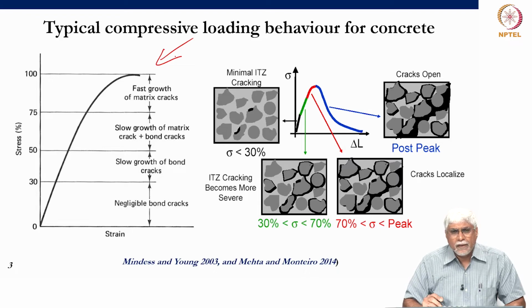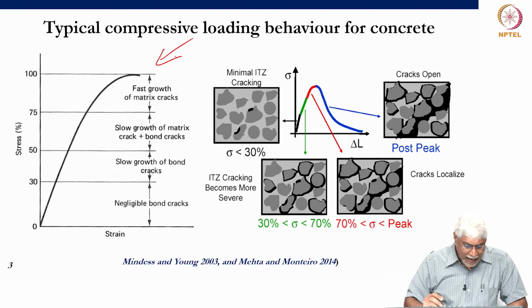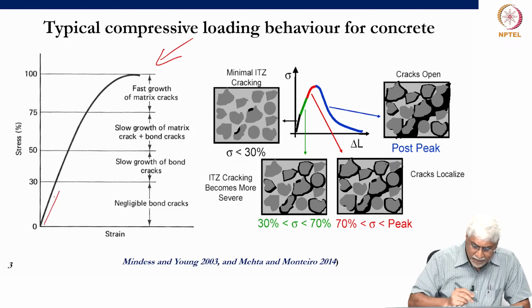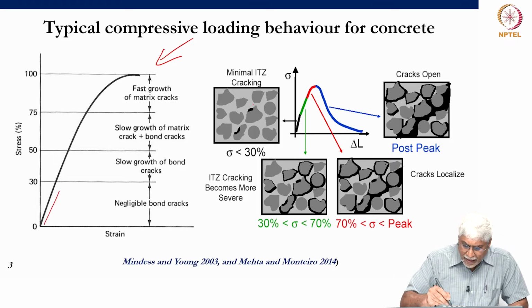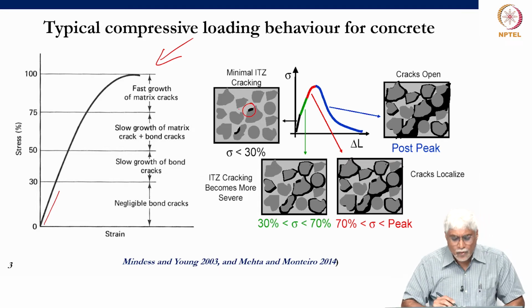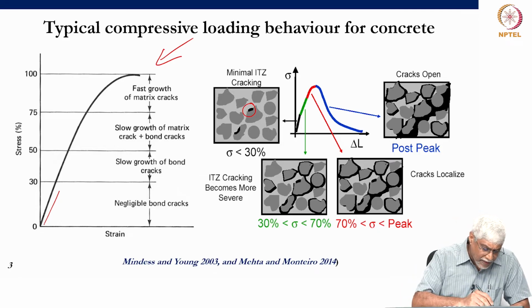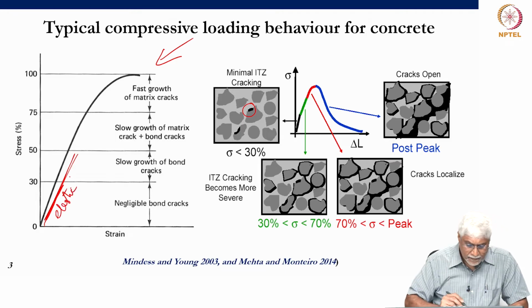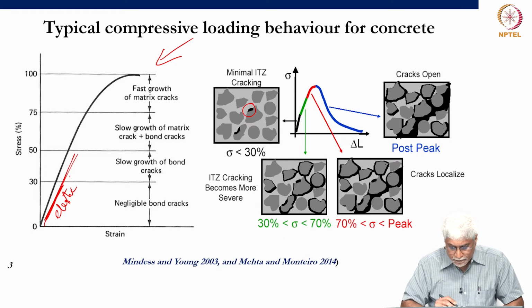Initially, there may be some defects, or if it's a very good concrete, normally the high strength concretes will have very few defects. And as we load the concrete, we have some of these defects opening up. Some of these defects will open up and propagate, but it's quite few of them which are doing this. So, we have basically an elastic behavior. So, this is basically elastic response, and if you unload, it goes back to 0.